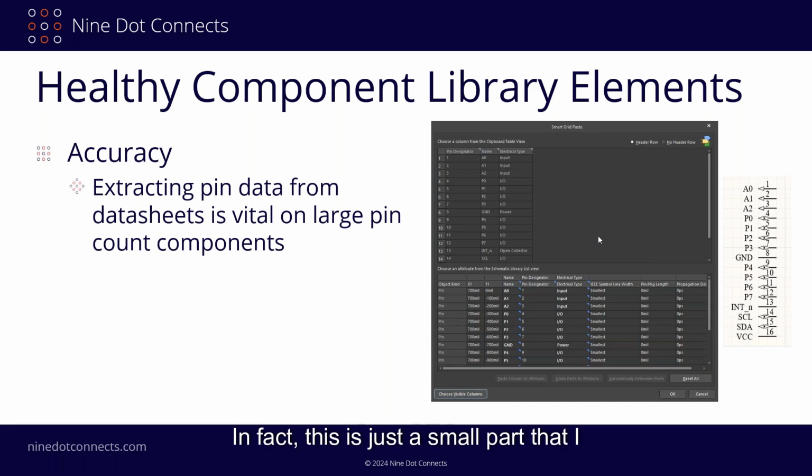In fact, this is just a small part, but I actually had a 400 pin part one time that I had to create from scratch. I was able to extract that data out of the data sheet and put it into the component, and I never had to type in a single number or pin name into the entire part. So whatever the data sheet was, it is. If you're not using the Smart Grid Paste feature, go out and learn about it because it's very, very helpful if you're going to build large components, large symbols.